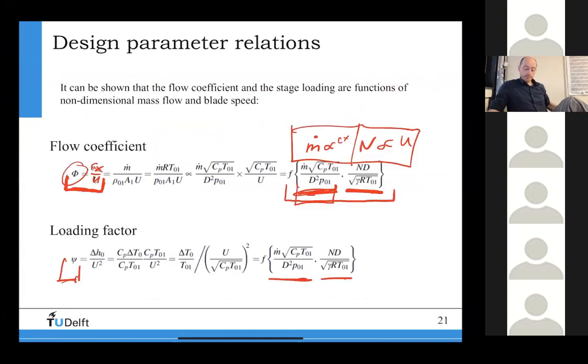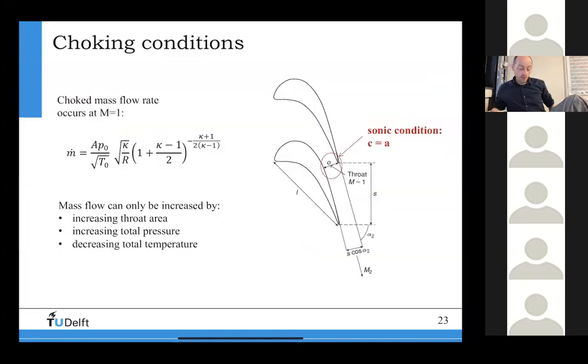And so how does this now work if you have these new parameters and you would like to come up with a turbine map or a compressor map? The first thing that we need to discuss for the turbine, which has already been mentioned in one of the previous classes, is that turbines are most of the time choked, right? They're choked. So you have here the combustion chamber. Let's say here you have a flame sitting here and then it burns, and then the hot flue gas goes into this turbine here.